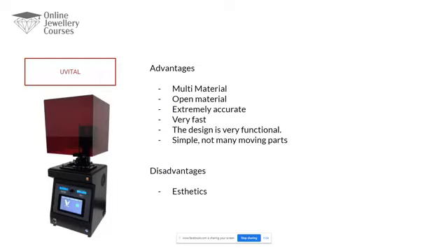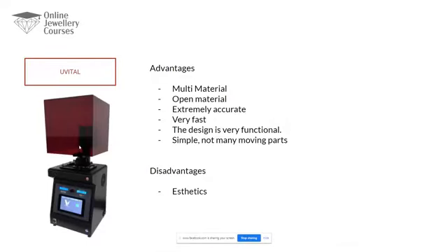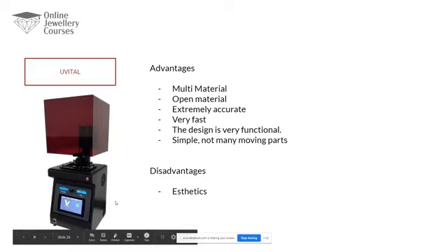The design has been designed in a way that, for example, you see this little ugly shape here? This is designed so that when you take the tray and the waxes out of the printer, you will always have a bit of a leak. You will have some resin pouring down. It's like gravity, you can't help it. Because of this design, what you avoid is the resin going on the screen. It's something silly, but it makes a difference. And the whole printer has been designed with this mentality in mind.